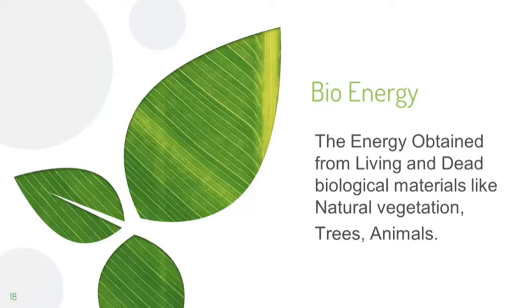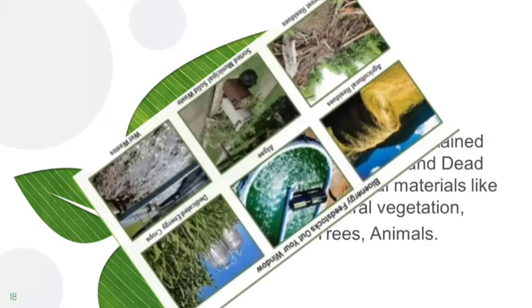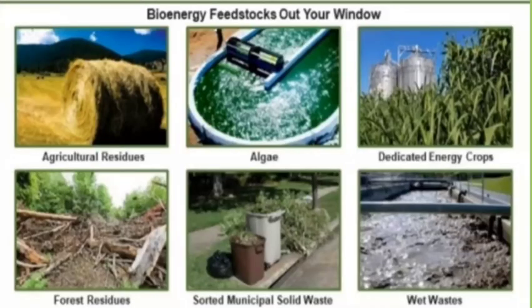The bioenergy technologies allow us to convert the solar energy stored in plants, foods, waste, farm waste, forest waste and algae into heat, electricity and fuel by using a variety of approaches like direct combustion methods and fermentation methods. In the direct combustion, we get energy from the solid waste. Here, waste material is burnt in confined containers to get energy.